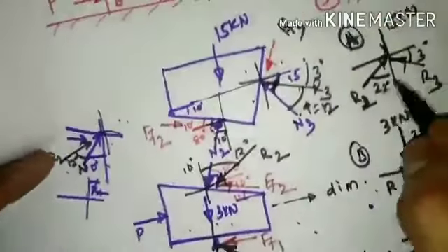Here, 22 degrees with respect to the y-axis and 3 degrees with respect to the x-axis. So the same inclinations have been represented here. Now to solve this, since there are 3 forces and all 3 forces are concurrent, we will be applying Lami's theorem.